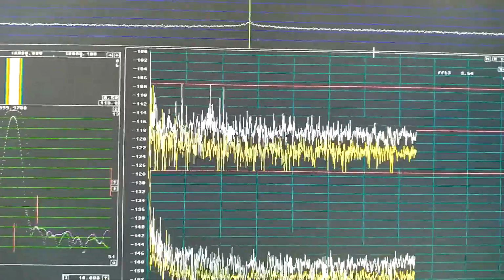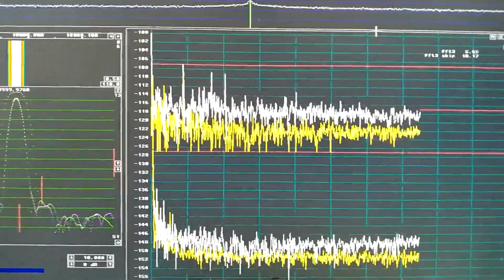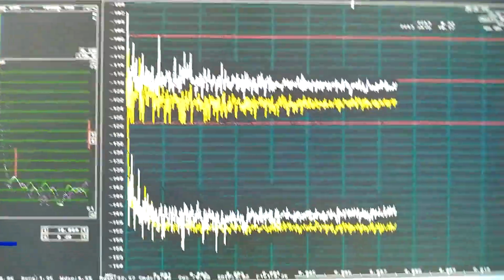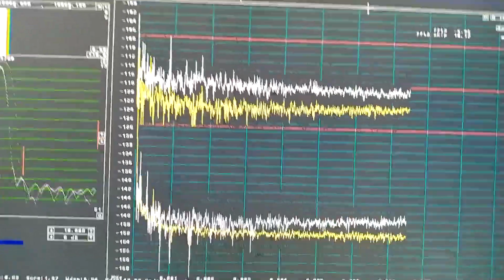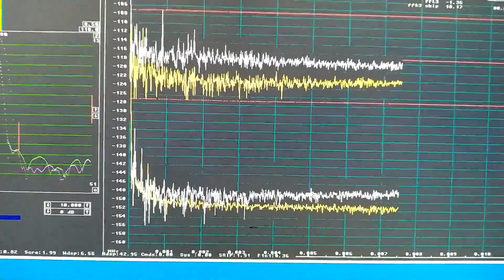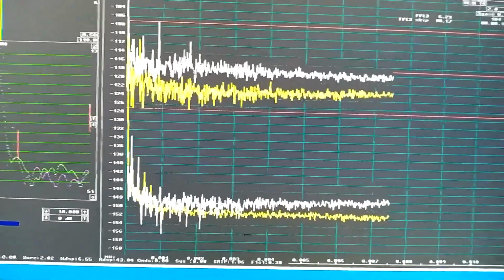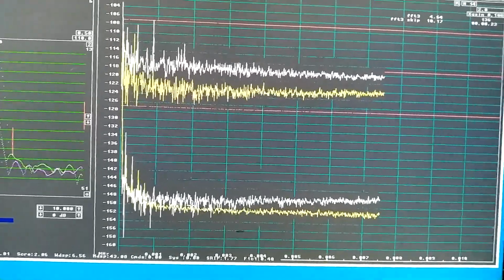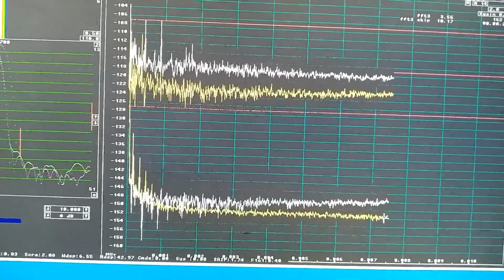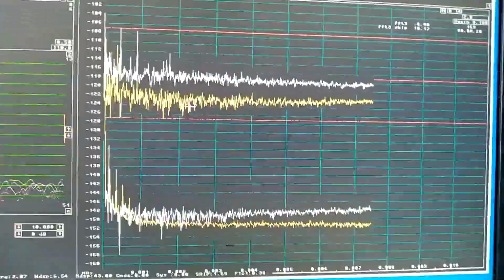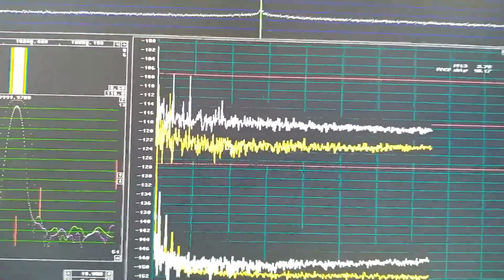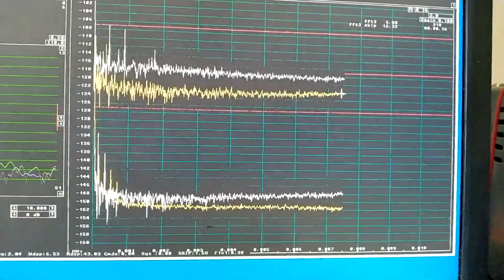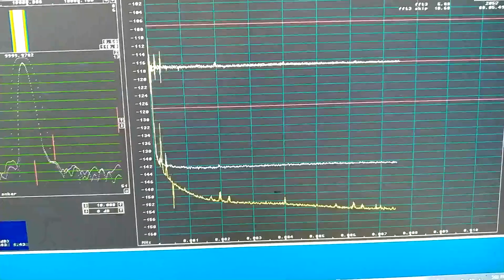I have changed the settings so I can see the wide range noise rapidly. And you can see now, after 15 seconds, I already have a pretty accurate measurement. I can see the amplitude noise is growing with frequency, while the phase noise is decreasing slowly. The correlation seems to be greatest at about 2 kHz, but it's still significant at the top frequency, 7.5 kilohertz.